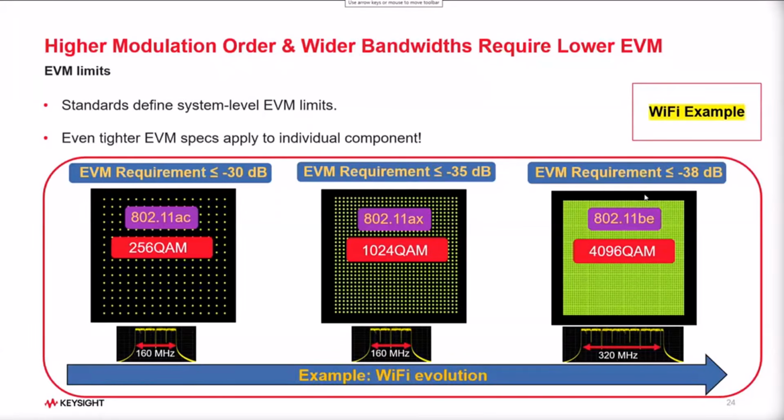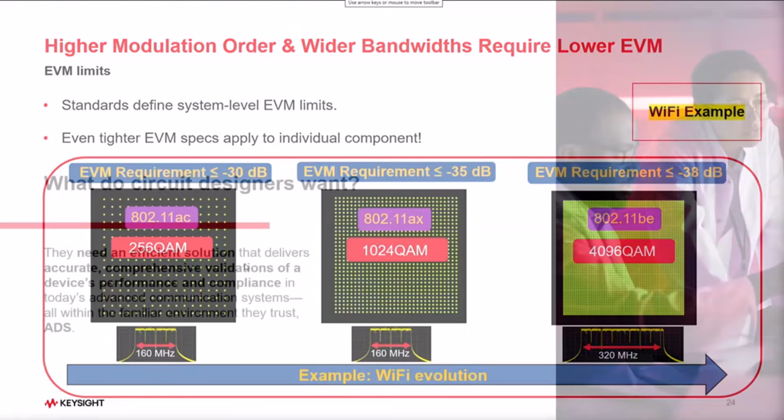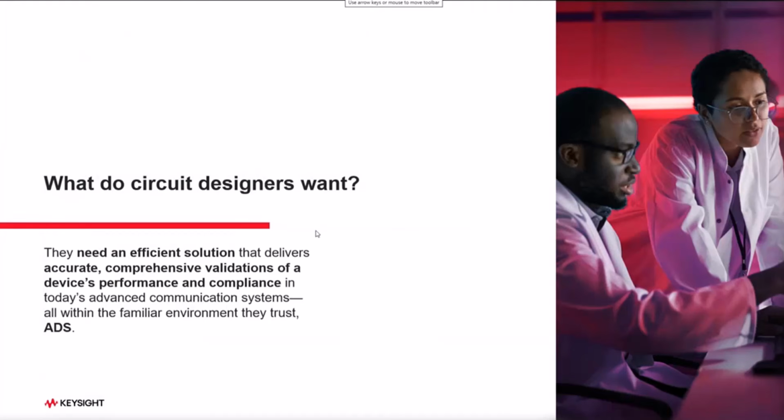So life is not getting simpler, because the wider the bandwidth and the denser the modulation, the more problematic it becomes. What that means is you can no longer rely on a one-tone or two-tone test. You really need to do modulation analysis.